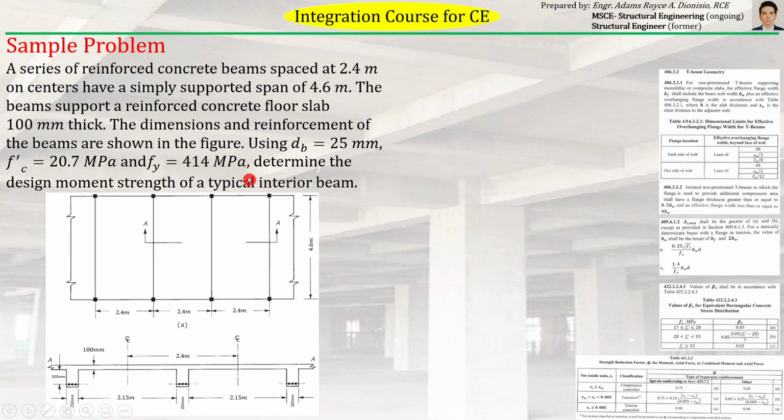Ang f'c ng concrete 20.7, and then ang fy ng steel 414 megapascal. And with that, given all of those information, the question asks for the design moment strength of a typical interior beam. So we will be investigating the design moment strength of an interior beam. So parang ito. When we say interior beam, beam siya na nasa loob.